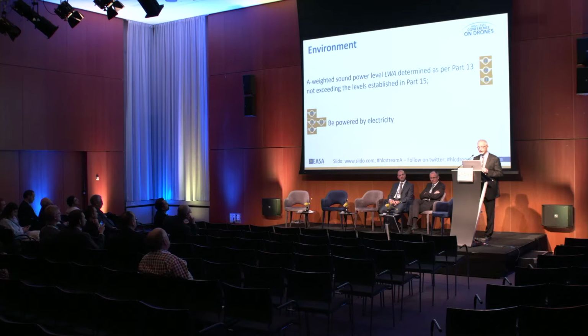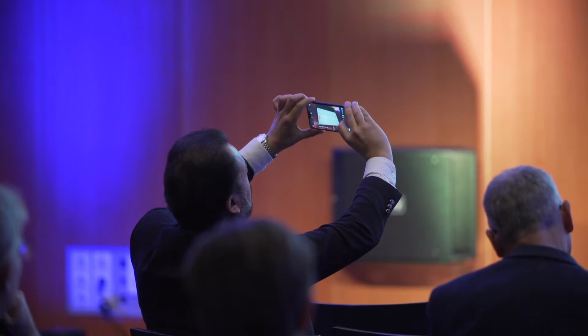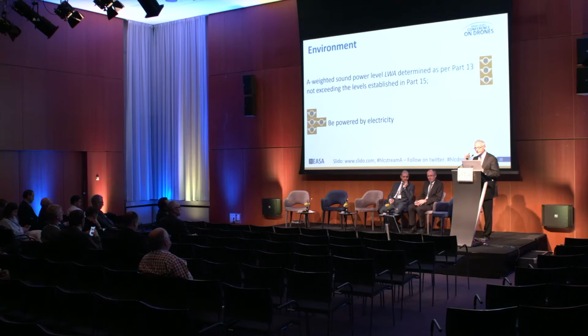Finally, we have environment, and we can remind two requirements. The one about noise, which says that the weighted sound power level, this LWA, is weighted according to the human sensibility. And in the delegated act, you find part 13 and part 15 that tells you how to measure and which levels are appropriate.